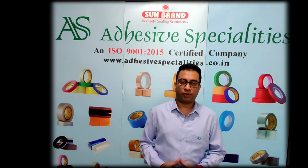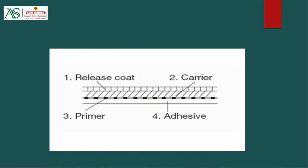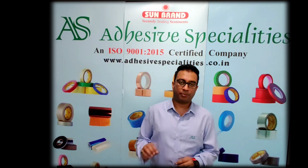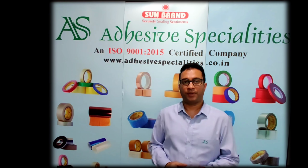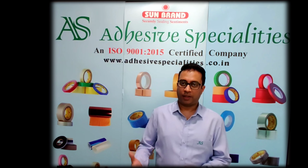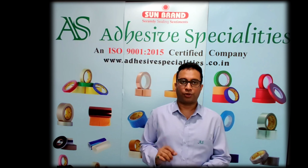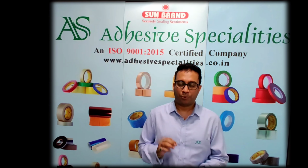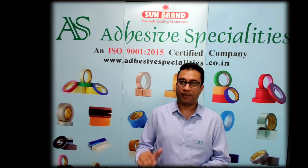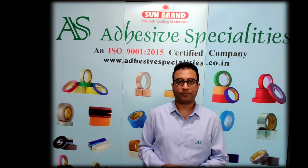What does the structure of a PSA look like? As you can see in this image, this is what a PSA looks like. One of the main components of PSA tapes is the carrier. The carrier is the support that we use for the tape. Here, we do a release coating on the surface of the carrier, which controls the unwinding force and the printability of tape. Then we do the priming and then the adhesive coating.